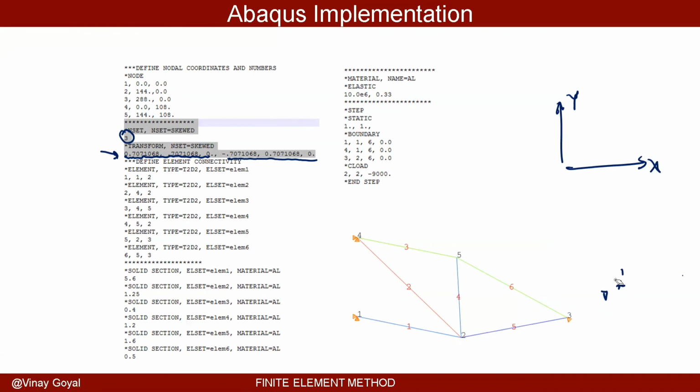provided is a different problem, right? We're not applying 6,000 pounds anymore on this node. We instead substituted that with a roller, and for that one, you put a degree of freedom here of 0. You put that degree of freedom as 0. You can see that there. It cannot move that way, right? So you're telling it for degree of freedom 2, which in the local orientation system for that node makes sense, it's 0, no deflection in that node.